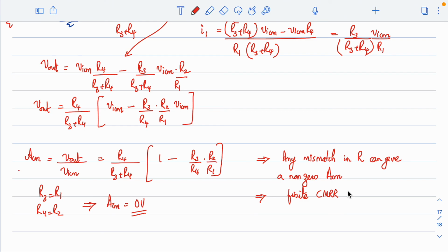but the value of the common mode rejection ratio also matters, because the higher the CMRR, it is better, because if you are not having a higher CMRR, the circuit is prone to noise, is the inference from the circuit, right? So this is how a differential amplifier works. What we have done with this differential amplifier is we have looked at both the common mode gain and the differential gain, and we can say that common mode gain should be as low as possible and differential gain should be as high as possible, right? So that's all about this differential amplifier.